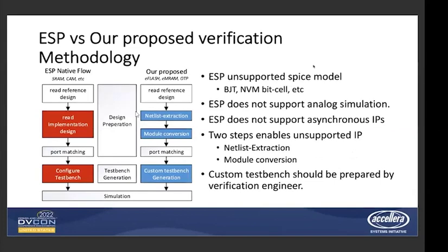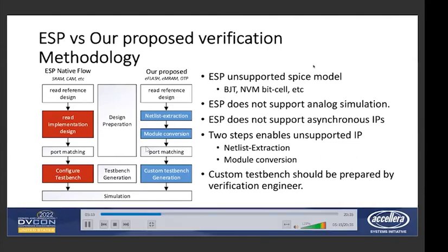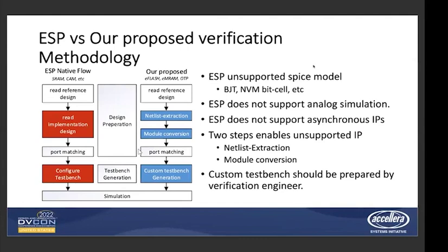So due to the limitation of ESP-supported IPs, we proposed our verification methodology for IPs not supported by the ESP tool. Using the Verilog versus Verilog comparison function of ESP and an extracted Verilog model from the netlist, we successfully compared the netlist and Verilog behavior model using our proposed methodology.